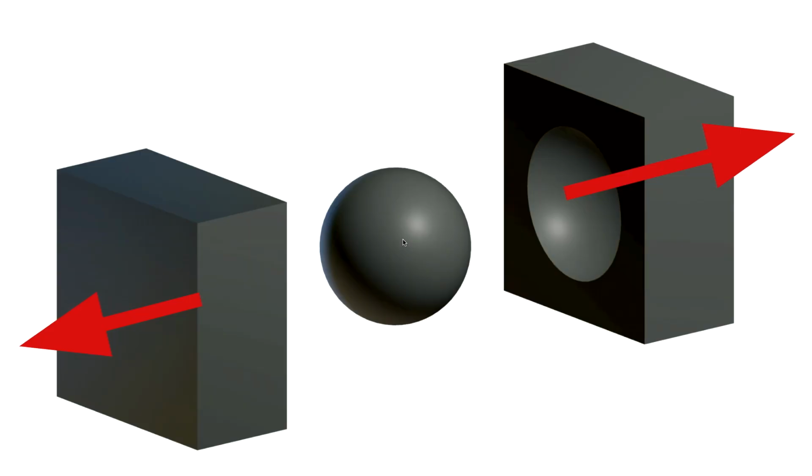Once the material hardens, the object must be removed from the mold. This often involves splitting the mold into at least two separate pieces. To ensure this process works smoothly, the geometry of the object must allow for clean removal with minimum friction so that the object is not going to break. This usually means designing the mold so it separates along one or two clear directions, and sometimes more. Though complex designs may require more.